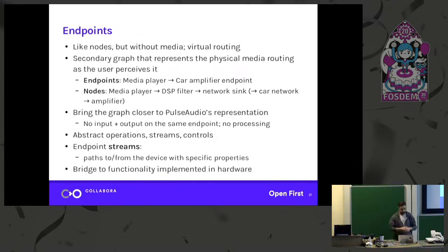So endpoints is a concept that I brought into PipeWire. It didn't exist before. PipeWire itself routes media through nodes from an application to a device or vice versa. But the thing is that in a car, you have all these kinds of streams, hardware streams, that maybe are not passing through the main CPU, and you want to control them. So I thought, how can we make an abstraction on top of all of these? And this is what the endpoints are.